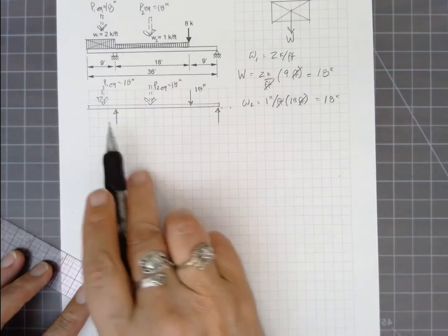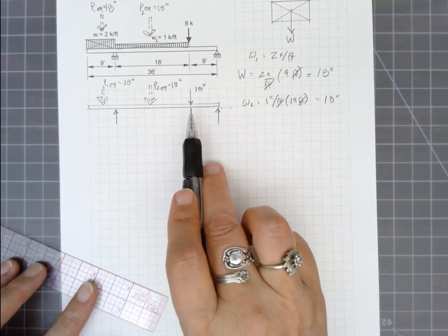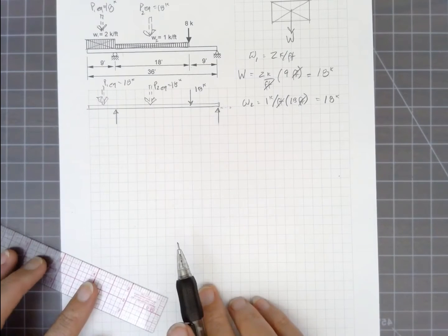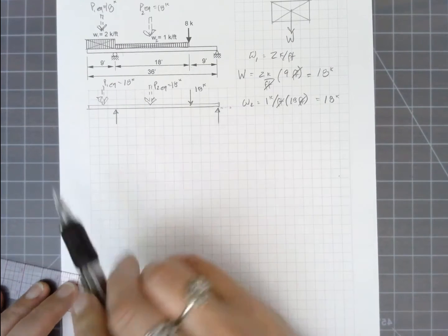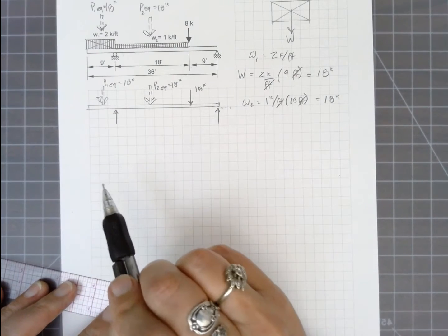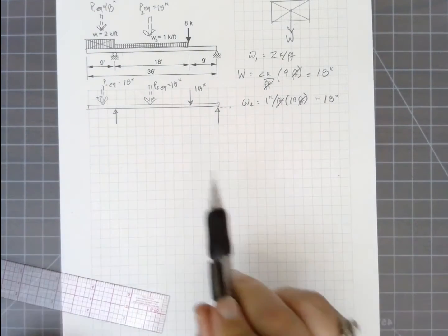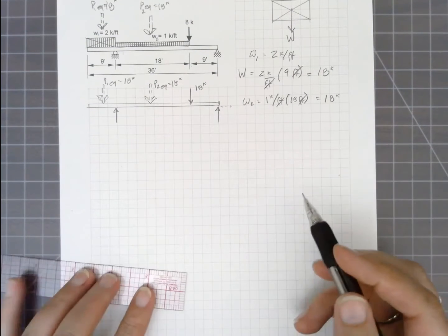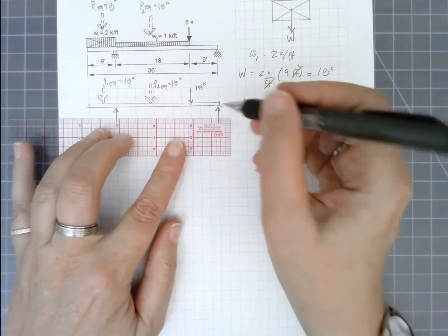And that's what it looks like. So it effectively behaves for the reactions in the same way as 3 concentrated loads, keeping in mind that this is not a concentrated load in reality. Now, in almost every engineering textbook you will find, this step is not done separately. It's just simply combined into the moment equation to calculate the total force. But we're separating it here for clarity.